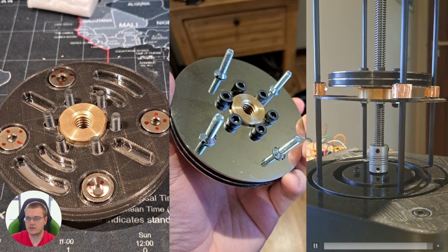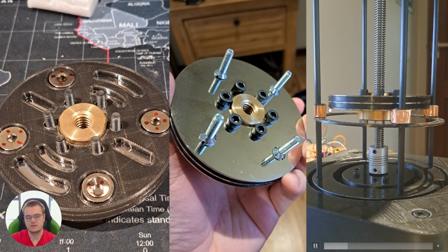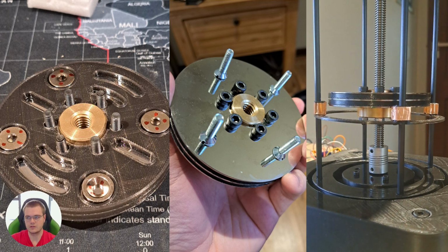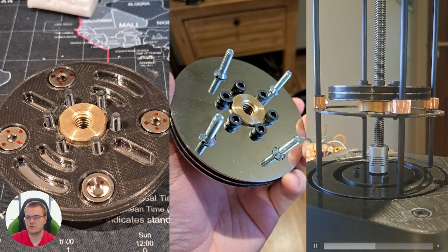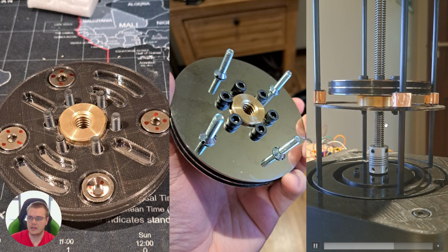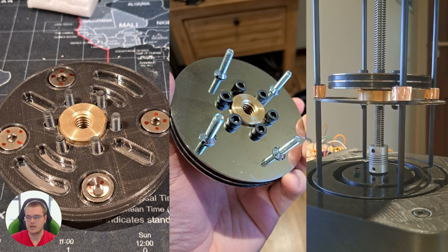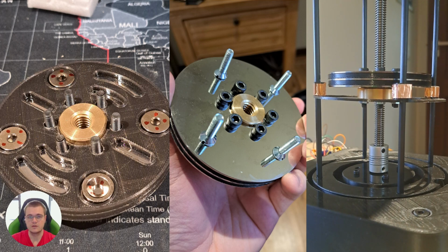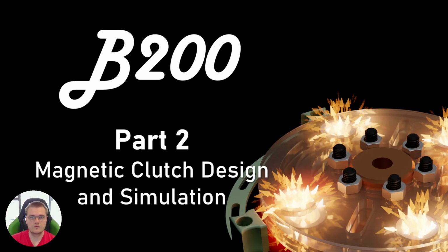Also note that the magnetic clutch is positioned down from the assembly disc by some distance, and that's due to where the stable region is between the force of gravity pulling the magnetic clutch down and a force trying to pull it back up, with the coupling between these magnets and the ones in the disc assembly. That works both for an up and down orientation, and the layout of the magnets is perfectly symmetrical, so that the weight distribution is also symmetrical, so we don't get any funny behavior as the disc moves up and down. So that's it for the clutch assembly.